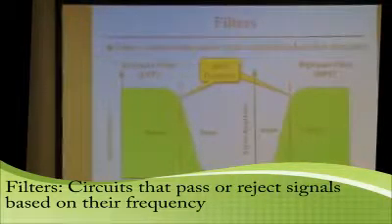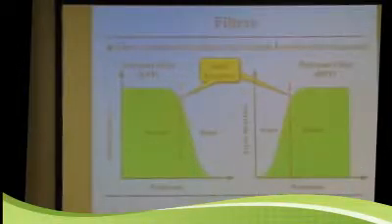And the harmonics are naturally not as strong as the principal or primary frequency. But still, they can be strong enough. If the principal frequency is at 100 watts, they might be at 5 watts. But you can communicate around the world on 5 watts. So you don't want that to happen. So what you do is you come up with filters, among other things, to filter out the frequencies that you don't want and pass through the frequency that you want.